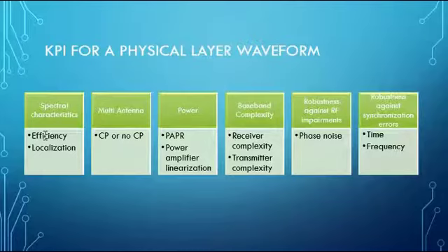Good time localization is required in order to enable low latency, especially in an adaptive TDD system with the need of fast and flexible switching between the downlink and uplink. The waveform needs to enable this short switching time between downlink and uplink.